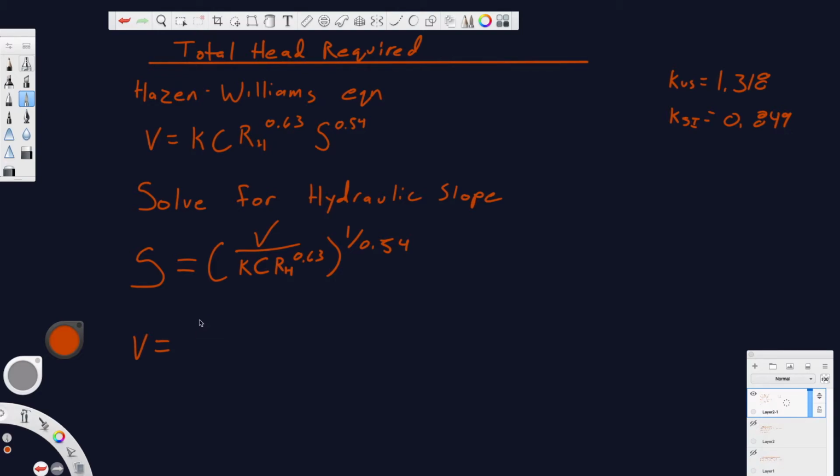Where the volumetric flow rate is, of course, volume per time. Well, if you divide the area of your pipe out of that volume, then you have a velocity. That's basically any particular molecule of water is going to be moving at this velocity. If you have an area of those, then per time it creates a volume.